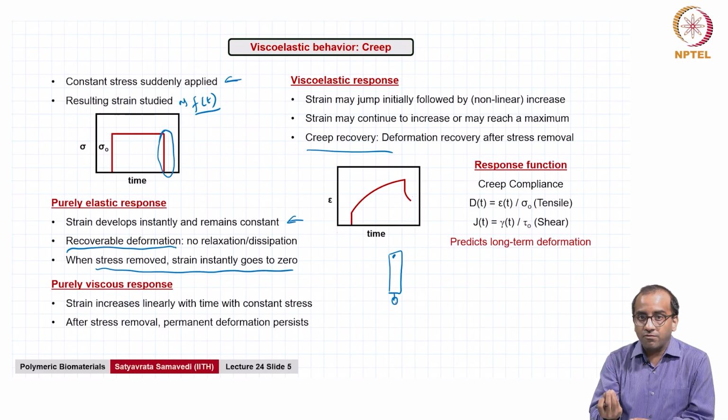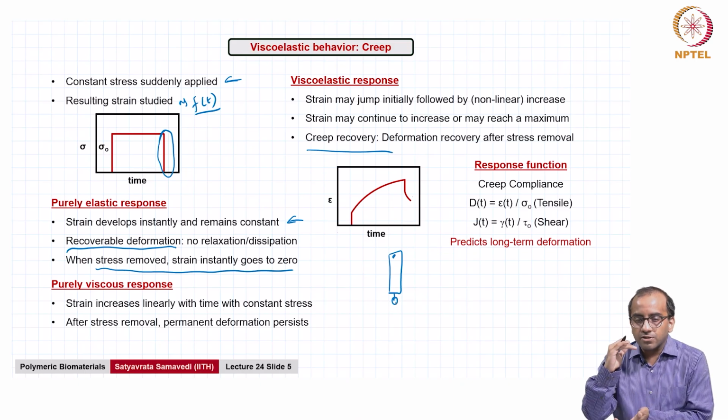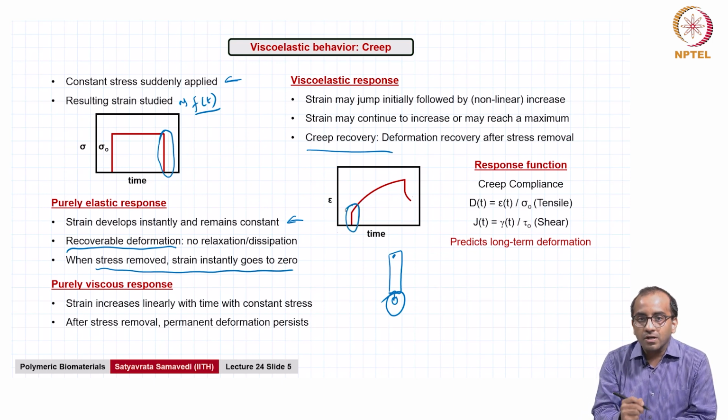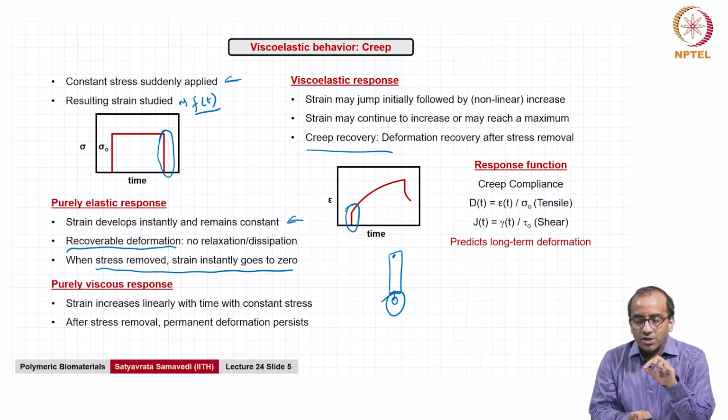So you will see a quick deformation initially, but then if you track it over time, come back every day and measure it with a ruler, you will see that under a constant load or a constant stress, the material will continue to deform. Apart from the initial deformation you got, which is largely the elastic kind of response as shown here, you will see an immediate elongation, but then with time over many days the deformation will slowly continue. And if you remove the load, you will see some kind of a recovery as shown here.